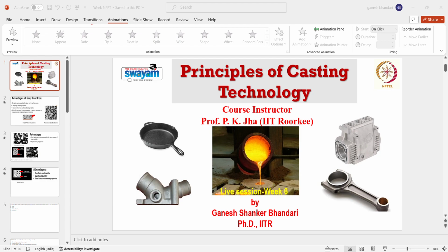Those elements will provide foreign particles to the system. Due to those foreign particles or the alloying elements inside the system, the solidification will start as early as possible because they provide the surface to form the nucleations.